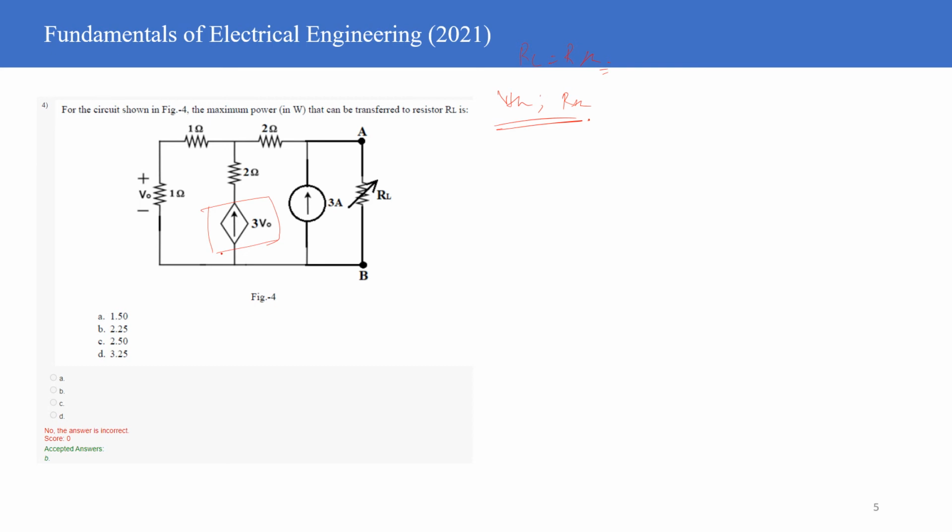So we'll make use of it. Previously we solved for V Thevenin and found it to be equal to 0, and therefore we did not have to calculate the R Thevenin in the previous case. I have not calculated the R Thevenin in the previous questions, so just for the sake of calculating R Thevenin, let's proceed with this particular calculation first.